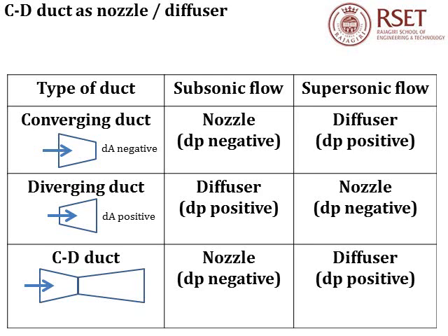Now whether it moves as a subsonic flow or has a supersonic flow depends on the conditions prevailing at the exit of the diverging duct. So apart from the condition that Mach number should be equal to 1 at the throat, there has to be other conditions which has to be met for the diverging duct of the CD duct to act as a nozzle. We will discuss these points in the upcoming slide when we deal with how a CD duct behaves towards varying back pressure.